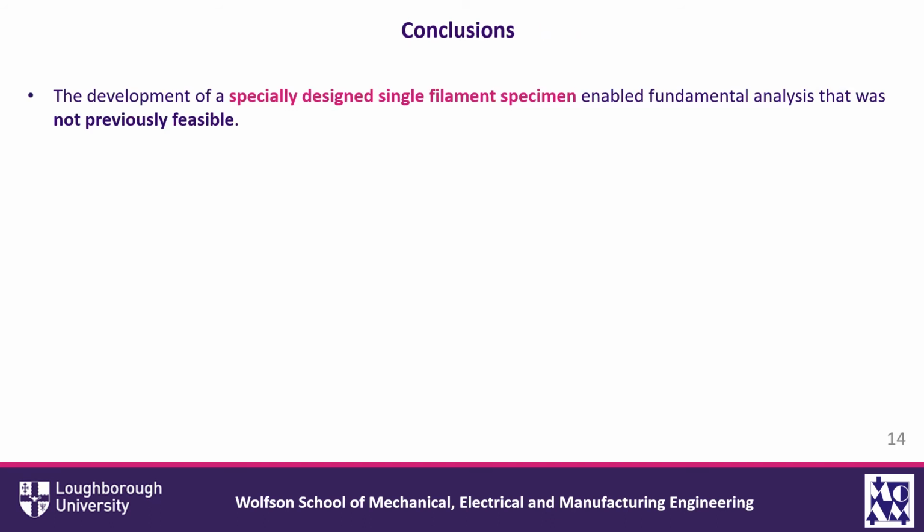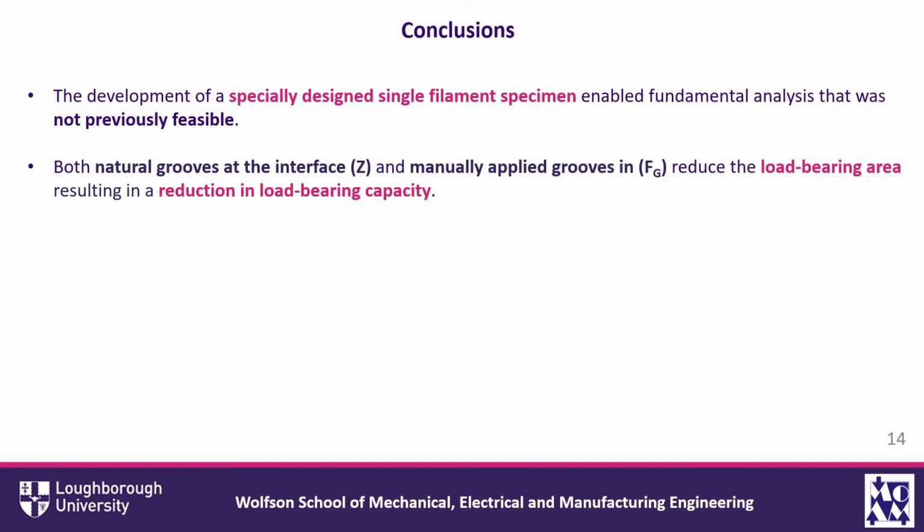To conclude this presentation, the specially designed single filament specimen that we've developed enables far more fundamental analysis of mechanical performance in 3D printed parts, which previously has been limited due to the more complex geometries that have been utilized. We were able to identify, using our specimen, that the natural grooves at the interface and those manually incorporated reduced the load-bearing area, which resulted in a reduction in load-bearing capacity.